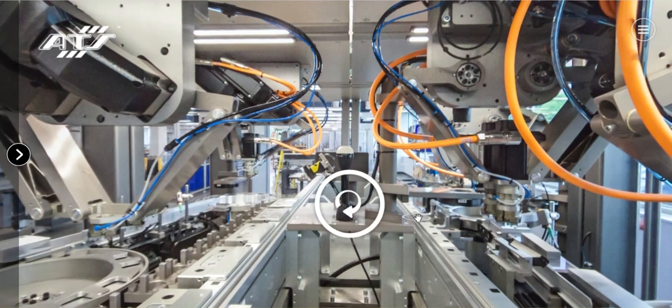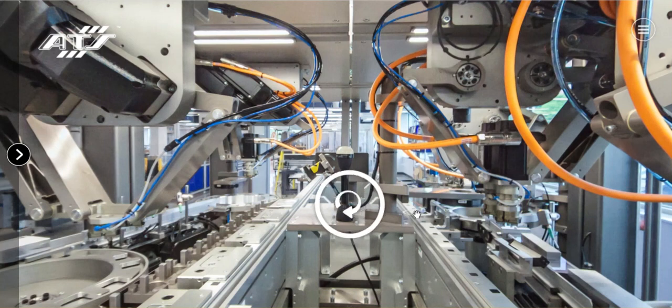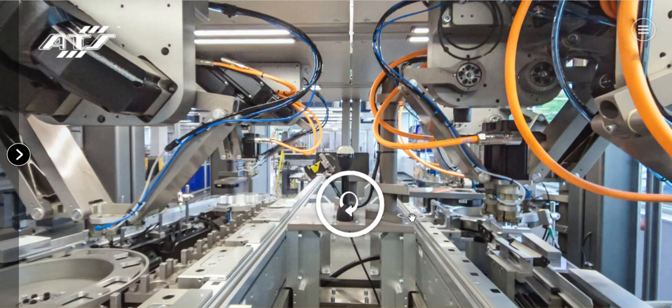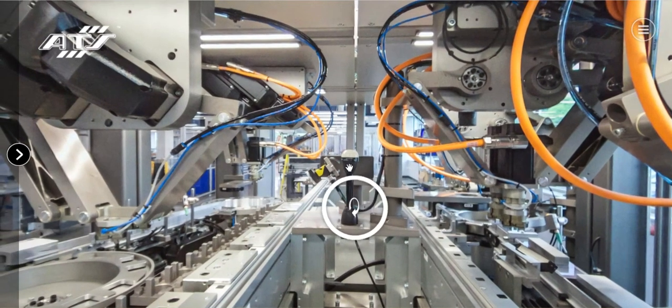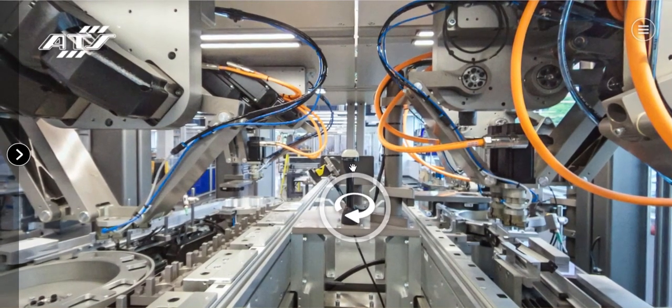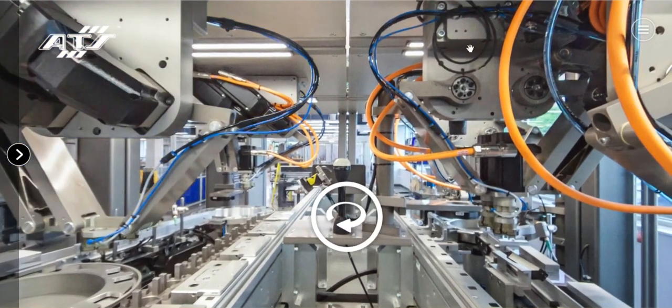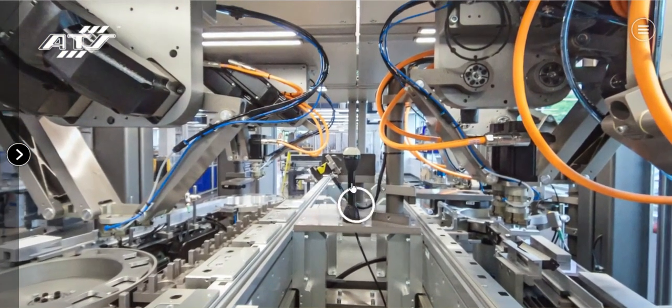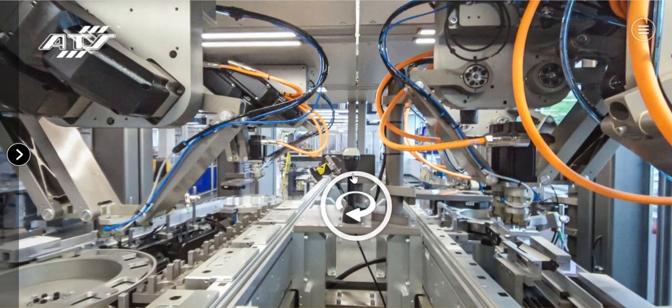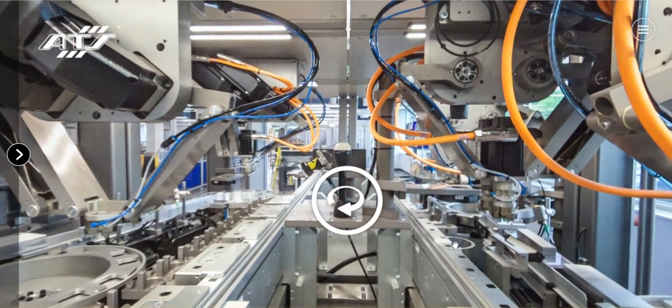When we want to restart the machine, because of the possibility of this manual intervention, it could be the case that things are not put into good starting positions to allow the machine to start back up. And that's what these indicator lights are for; you'll see indicator lights again here. This one corresponds to the pallet. Each individual robot has a similar indicator light on it. This light will change colors depending on whether or not pallets are in a position safe to restart the machine.